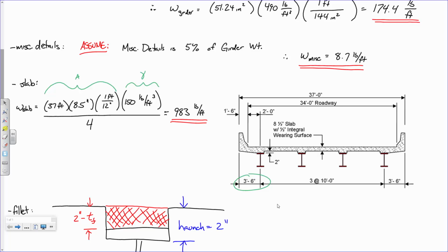There's a barrier. This is kind of a stupid question, but would you not need to account for the steel that's going into the reinforced concrete? Now we talked about that. No, we did, I just can't remember what. We use 150 pounds per cubic foot as opposed to 145. Okay,